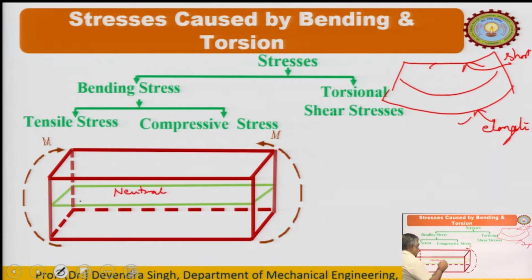The one shown in green, this is the neutral plane, in which there is neither elongation nor contraction. Yes, there is a curvature, and the axis and the line, the centroidal line at this plane, that is denoted by an A, that is called the centroidal axis, and the distances of fibers where we wish to calculate the stresses are always defined with respect to the neutral axis.